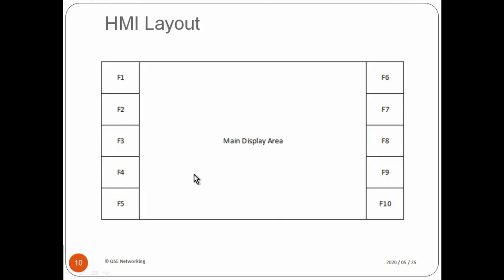Right, if you're working with HMIs, I'm not a fan of HMIs, but again, they have the same problem that the screen is quite small, and if you don't actually put function key displays on the screen, you don't know what the button does. So instead of putting F1 there, you might say menu or area 1, area 2, etc. But also notice now your screen gets even smaller on an already small screen. So making this text small and cryptic makes it a little bit difficult.